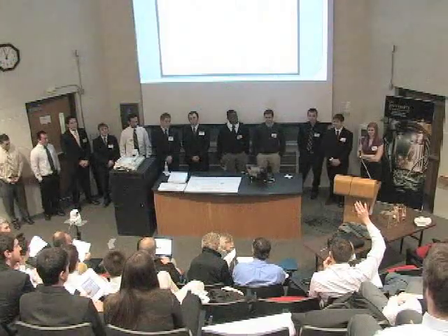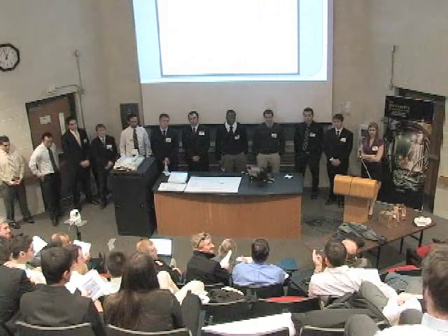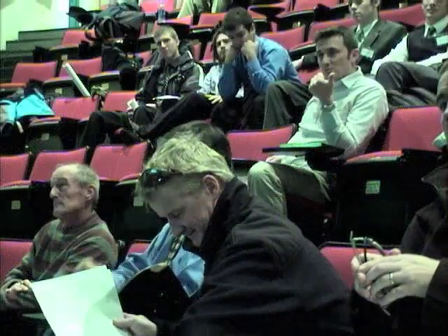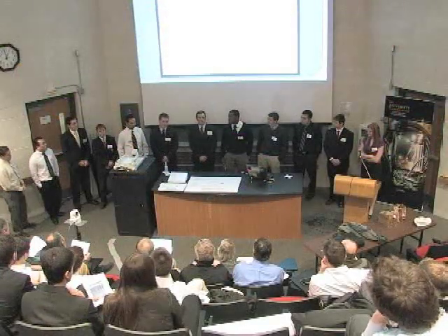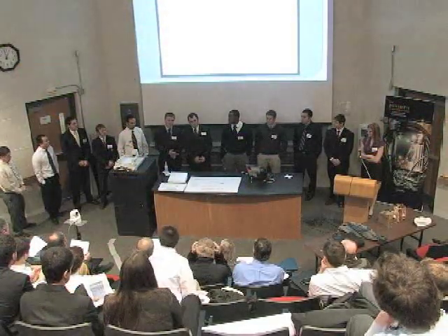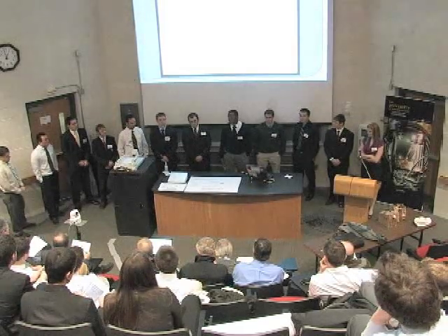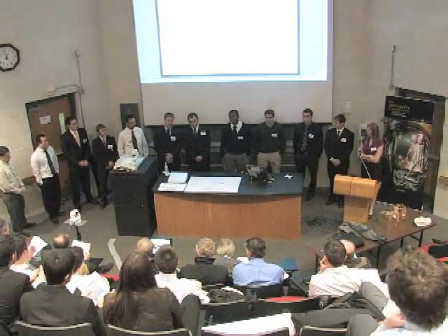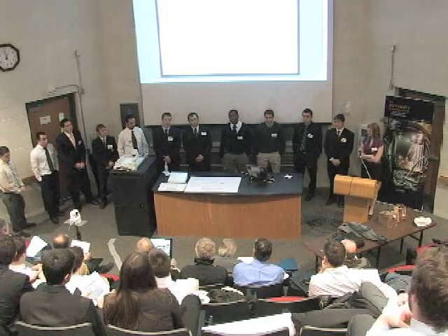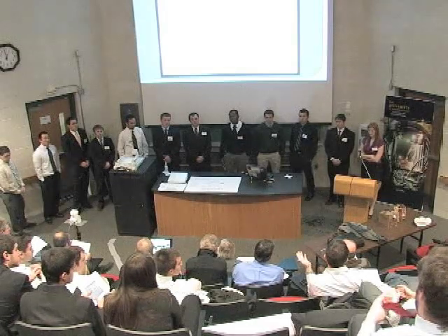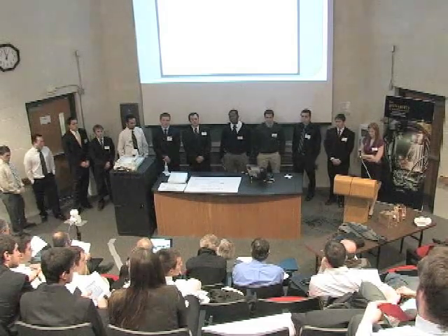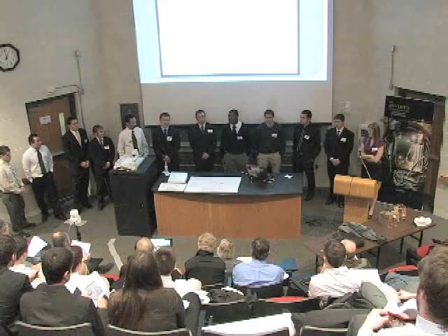Okay, so maybe one more question. I see Chris. So, quick question for Sam and Matt. One of your buildings is on piles, one is on shallow foundations. Why did you decide to go with deep foundations versus shallow foundations? Well, below our shops is an inconsistent fill layer, ranging from 15 to 45 to 15 again. So we figured the easier option was piles down to the very dense fill layer that's available. So you have some confidence that your fill is really dense in one area and maybe not so dense in another area. That's how we see it.